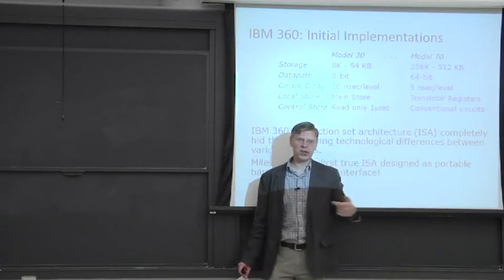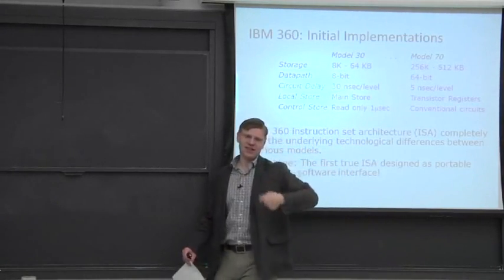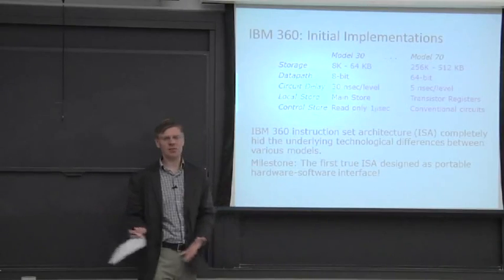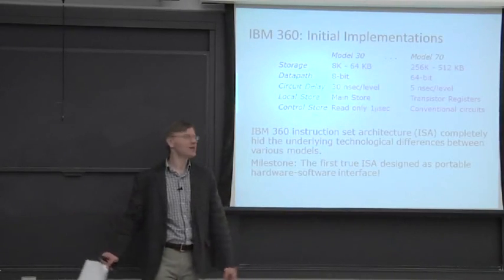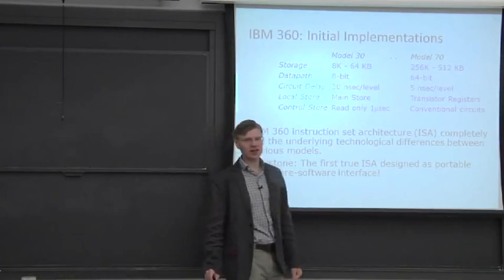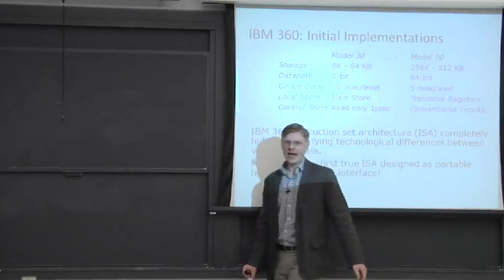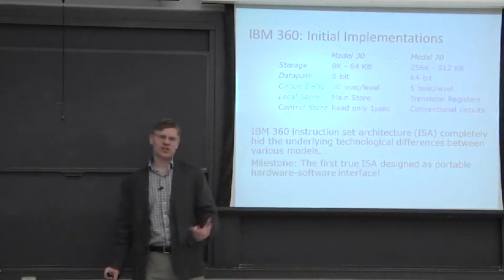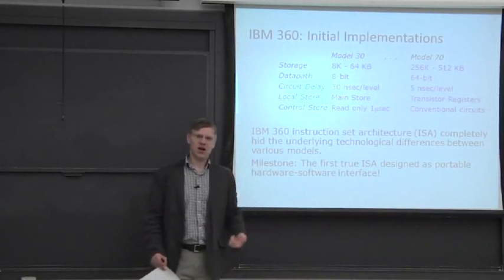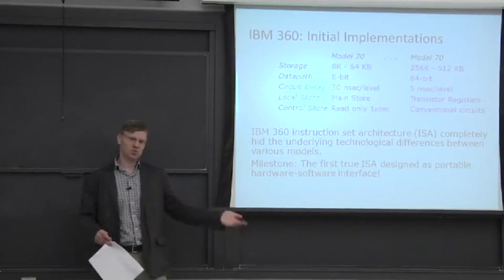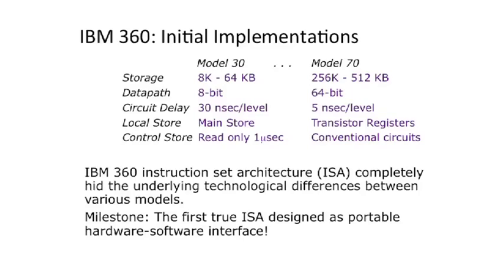And if it wanted to do a 64-bit operation, it had to do 8-bit operations to make up a 64-bit operation. And probably it actually even had to do more than that to handle all the carries correctly. Versus the high-end implementation had a full adder there, and it could actually do a 64-bit add by itself without having to do lots of micro-sequenced operations. And, oh, yes, with minor modifications, it lives on today.